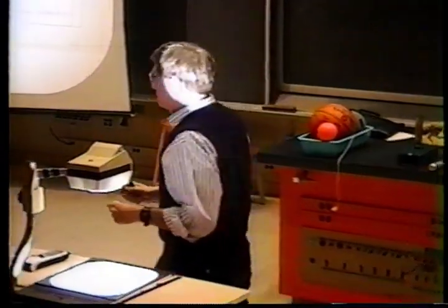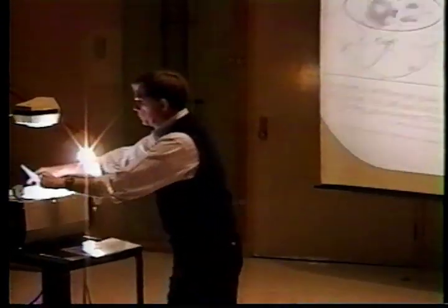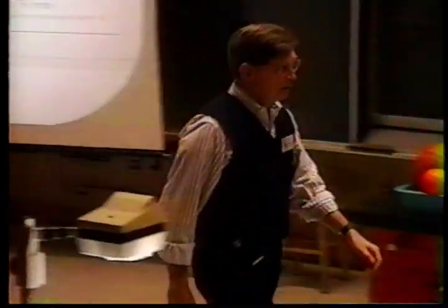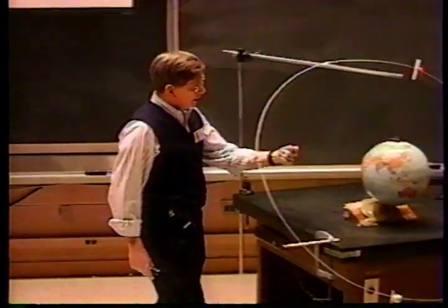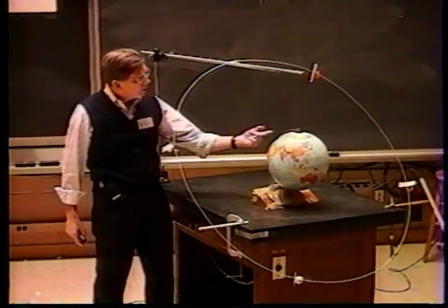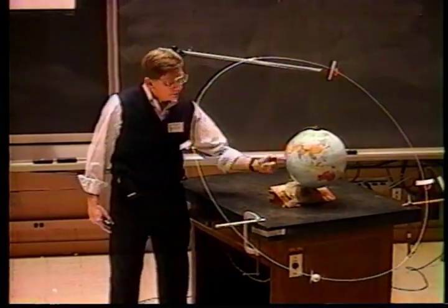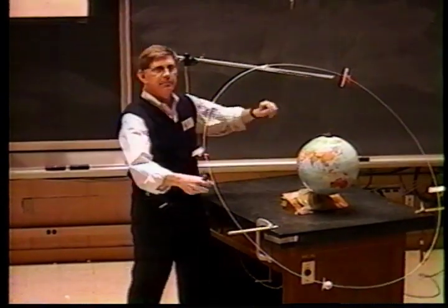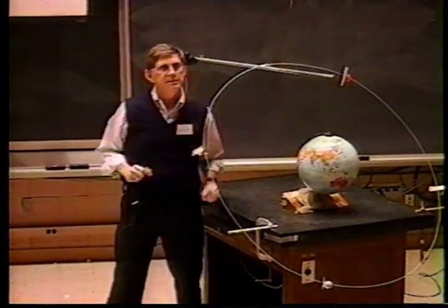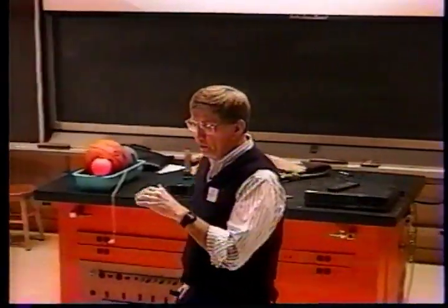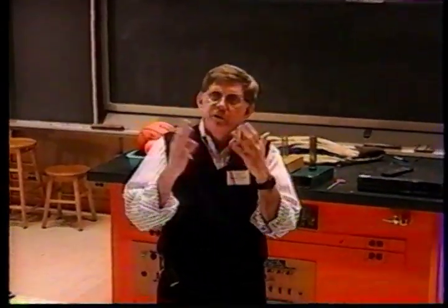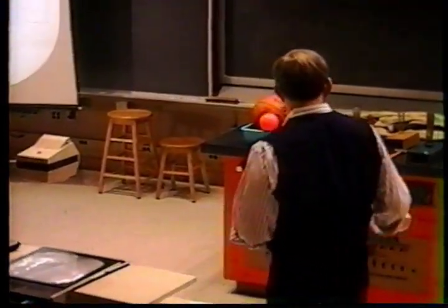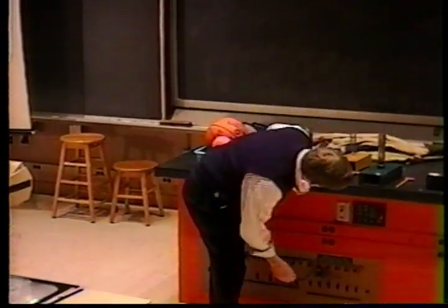It turns out in the long run that's been an unfortunate choice, because the satellites are going over the same ground tracks every second orbit over the same part of the Earth. They are affected by the same gravitational anomalies, Professor Chen's mountains and all that kind of stuff, and these satellites tend to bunch up, so they have to use rocket fuel to keep them spaced apart. If they had picked anything other than that number, the random process would have taken care of averaging out those gravitational effects due to the fact the Earth is not a perfect sphere.